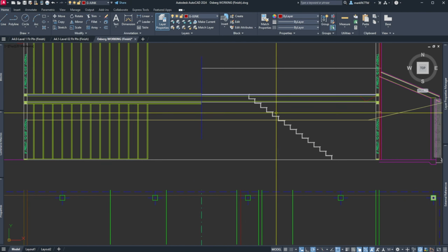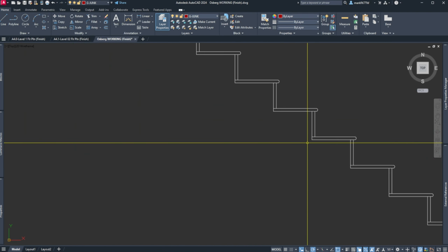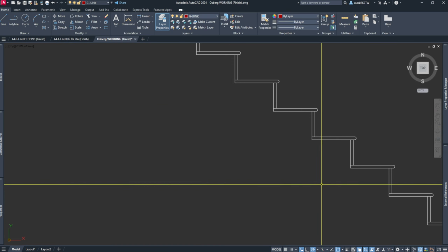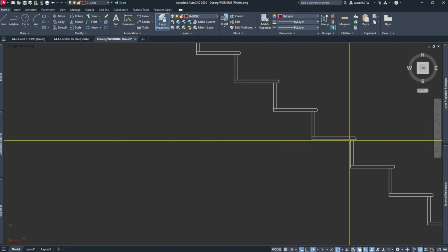And we have stairs, kind of. We need a little piece more. So we're going to make these stringers out of 2x12s, which is 11 and a quarter. Those of you not familiar with nominal, the 2x4 is 3.5, 2x6 is 5.5. And then when you get to 2x8, you go 7 and a quarter, and it stays quarter on up.